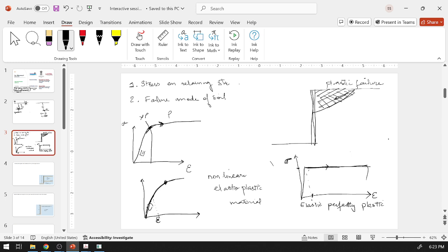And whatever we studied about shear strength, we draw this Mohr-Coulomb circle. Any soil state below this circle is an elastic soil state. If I take a soil state here, here, here, these are all elastic soil states because as soon as it touches this failure surface, this is a limiting state. And you should know that this kind of soil state is not admissible.